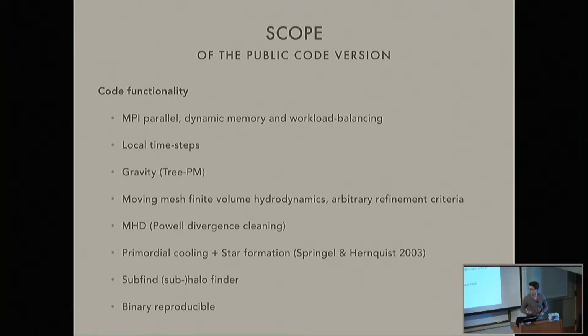And what this also comes with for cosmological simulations, which is quite a neat feature, is an on-the-fly halo and subhalo finder, which also orders the particle output, which becomes increasingly important as the data output becomes significant and quite hard to manage for the analysis of it. And one key feature which is often a bit underappreciated is that the code is binary reproducible once you run it again with the same number of MPI ranks.